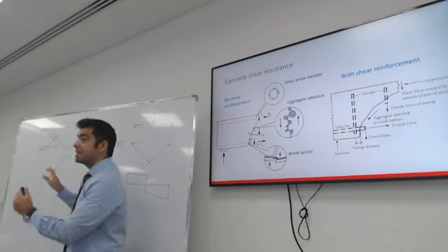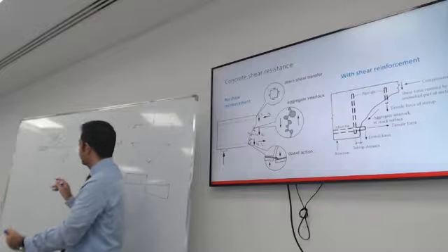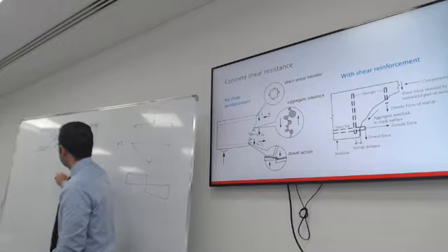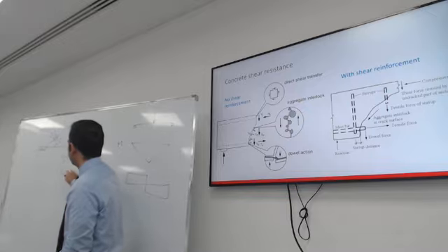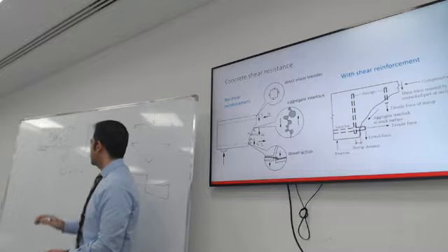There is such thing as a maximum spacing. Don't exceed the maximum spacing. We will learn how to calculate it. S maximum should not exceed 75% of d. Do you guys remember what d is?